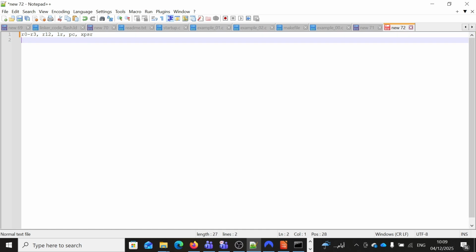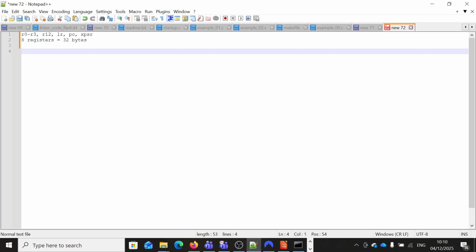So in total, we'll have 8 registers. Those will be the equivalent of 32 bytes. However, the stack pointer may not get decremented by only 32 bytes. If the final value of the stack pointer after getting decremented is not 8 bytes aligned, then the CPU may push a set of dummy bytes into the stack memory to preserve the 8 bytes alignment.